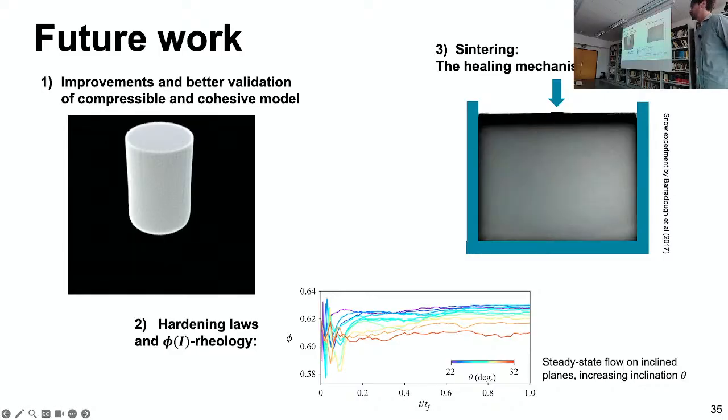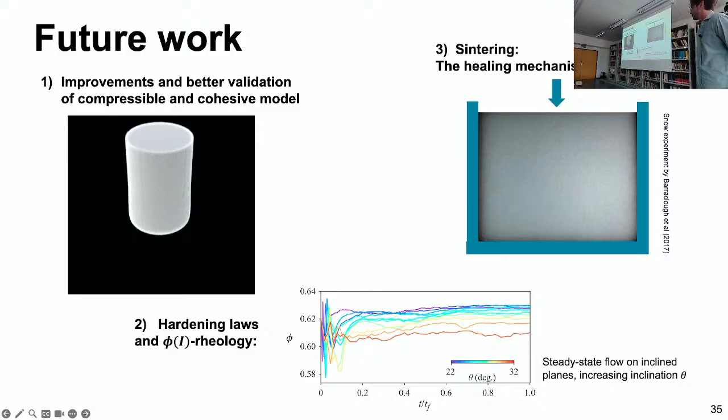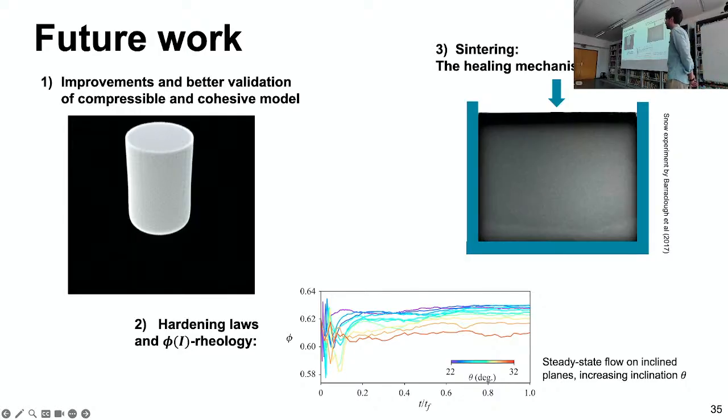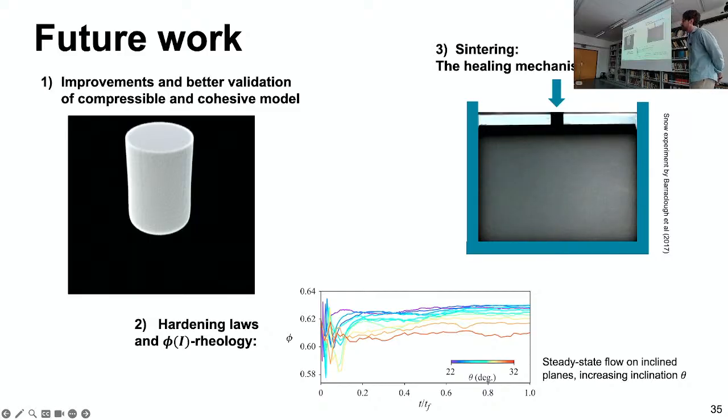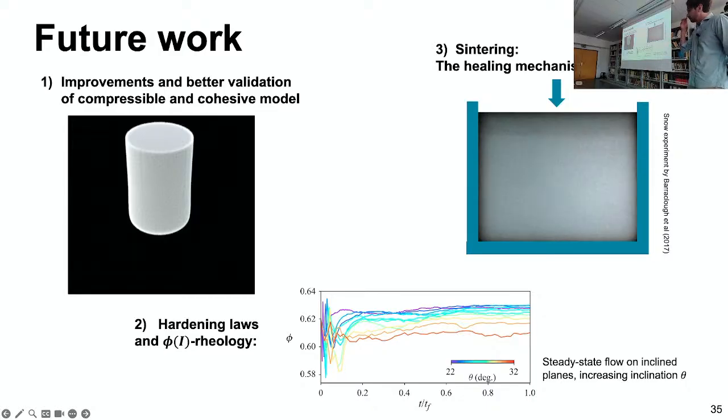Yeah, that of course is a good question, and it will also depend on what infrastructure you have and how many particles you are simulating. I think for the Blatten simulation, we're talking about a few hours. We have close to 1 million particles or so, so it's not the biggest simulation. We also have simulations that last a week or more. So it really depends. And because we're using an explicit method, it also depends on the parameters, because the Young's modulus will affect your time stepping.